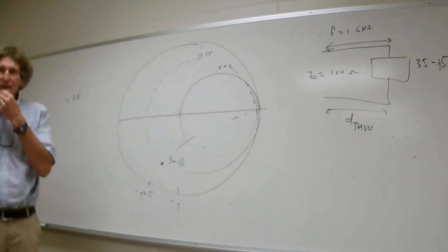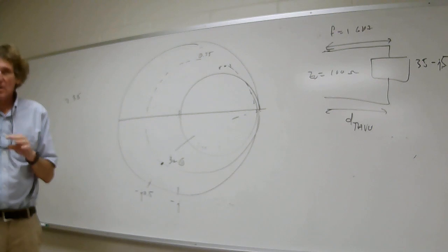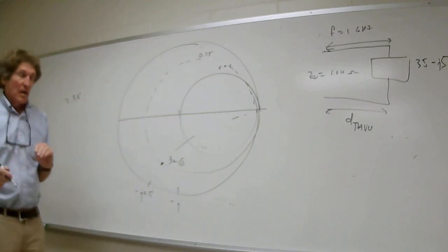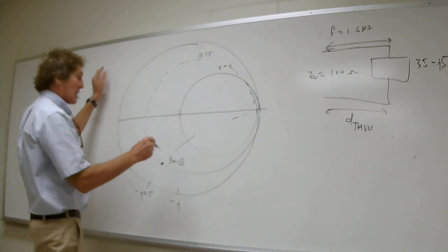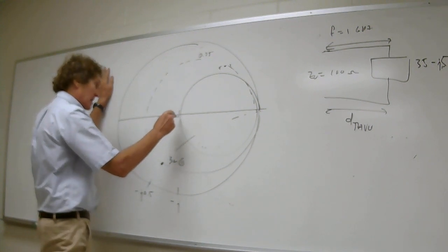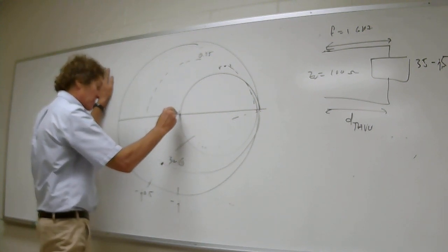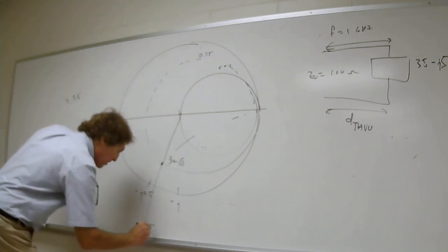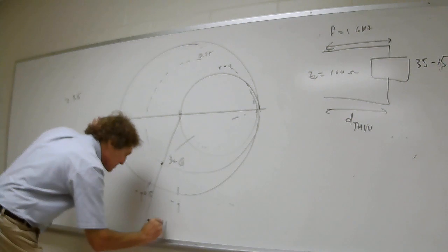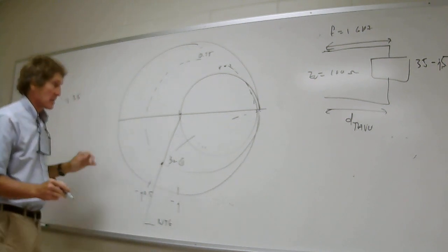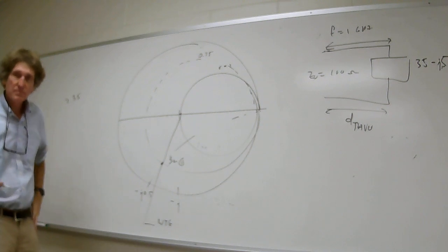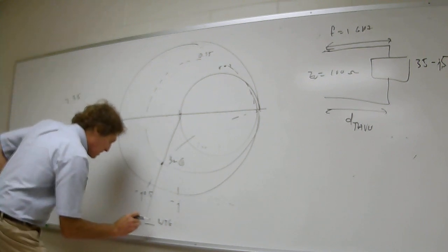All right, we're going to go through it again, and we're going to do it with transmission lines replacing this stuff. First of all, I have to take a line and go right from here through zL and shoot it out, and then I need the wavelengths towards generator reading right here. You can tell me from before: 0.4196 lambda. That's what I got.